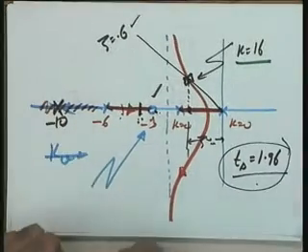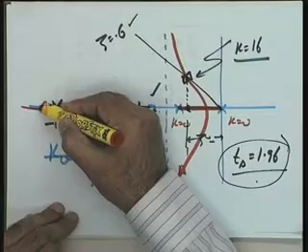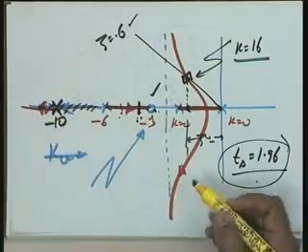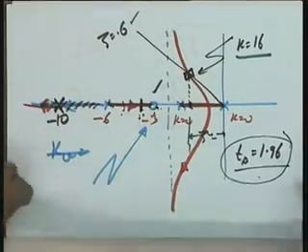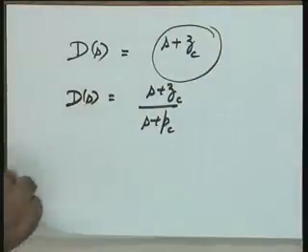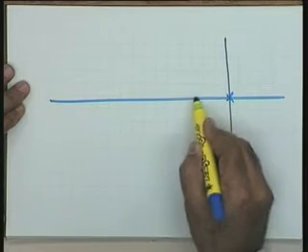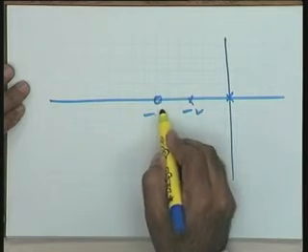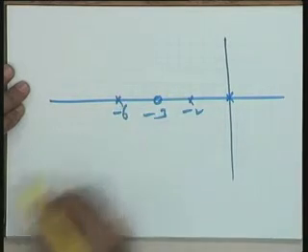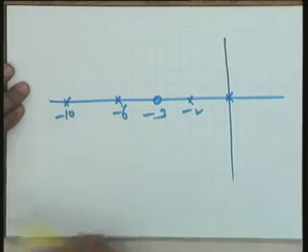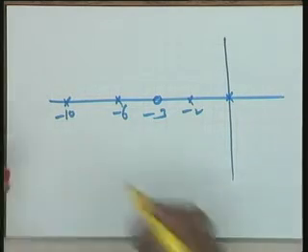The third pole, when added, will add one more root locus plot, and hence one more pole will be there, and your overall root locus diagram may look like this. Overall root locus diagram with the pole added. 0, minus 2, minus 3 is a zero, minus 6, a pole has been taken at minus 10. Let us make a root locus sketch.